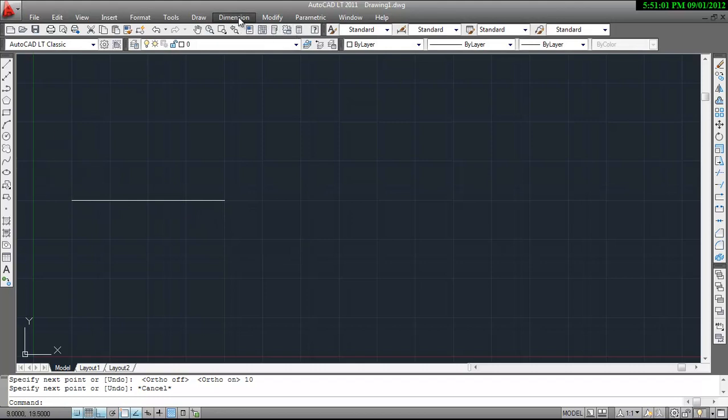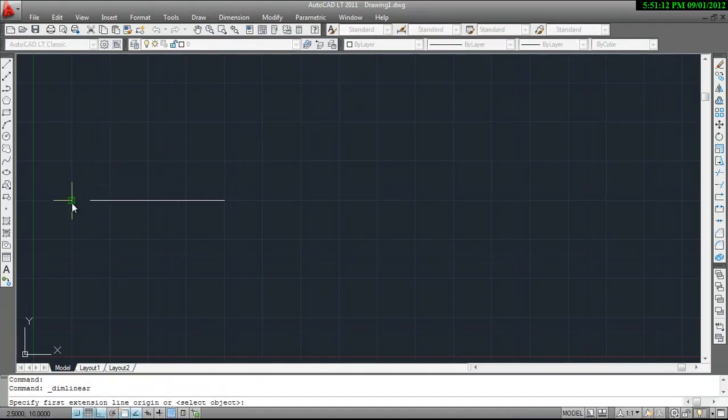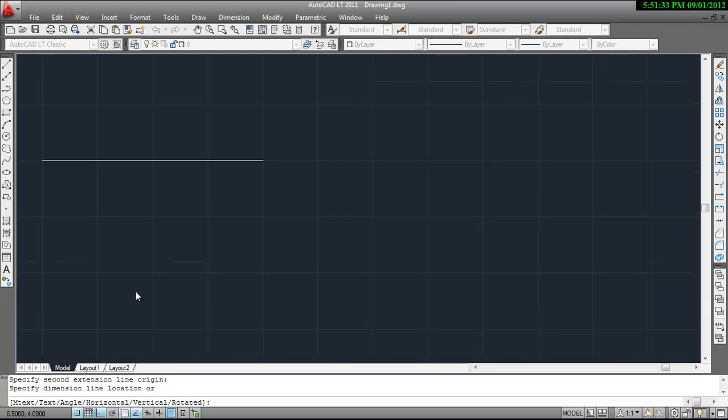If you don't believe me, you can see the dimensions of that. Here in the menu bar there is an option of dimensions. Go to linear dimensions. It will ask you about the first point, second point, drag it to, now keep it down. Now to zoom in, you can rotate your central mouse button forward, and to zoom out you can rotate it backward.